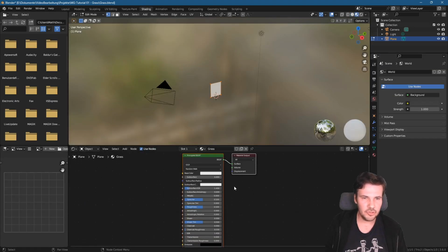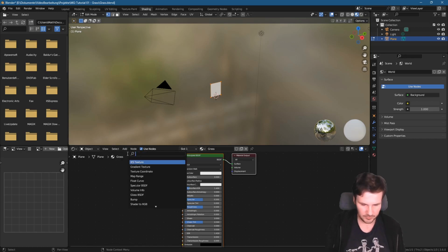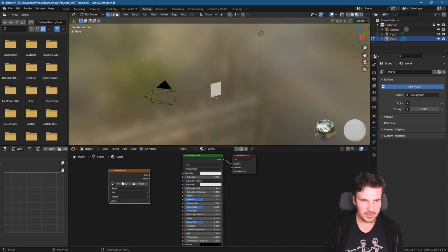Blender already shows some default nodes, Principled BSDF and Material Output. We leave them and we use them. We just add some more nodes. So click Add, Search, and type in Image and choose the node Image Texture and put it left to the Principled BSDF. Connect the output color of the image texture to the base color of the Principled BSDF.